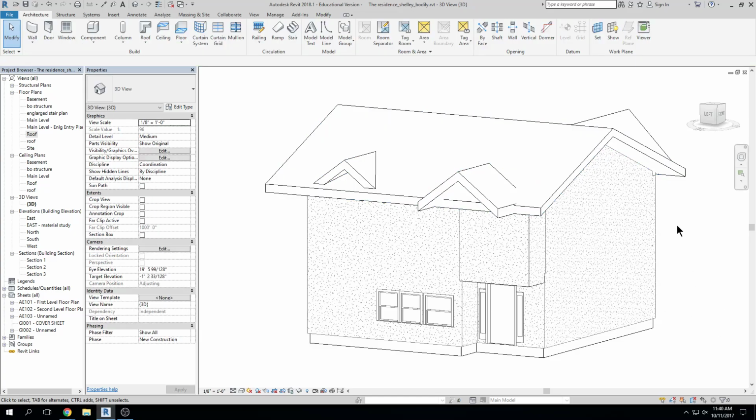If I were to talk about means and methods, it's likely better to use the join roof tool so that everything is nice and clean. Sometimes you want to get in a hurry and don't want to clean things up or cut holes in roofs because it takes time, and you're anticipating that maybe you're the only one that will be working in the model.